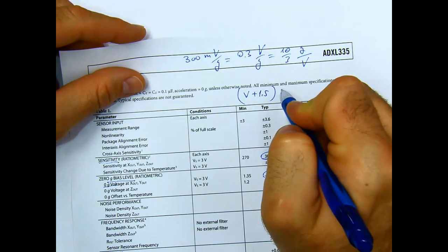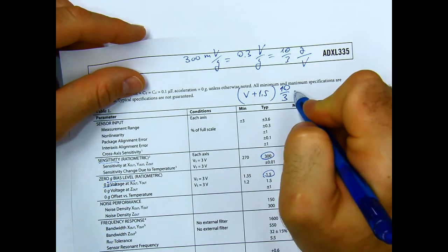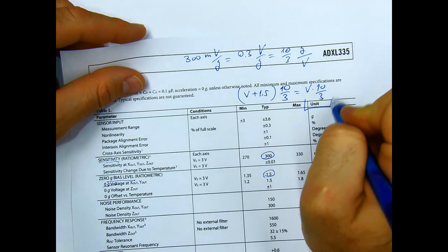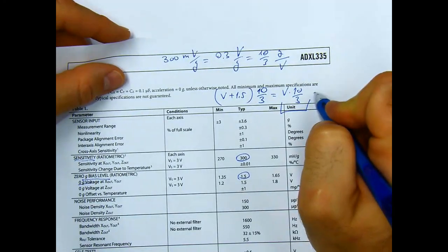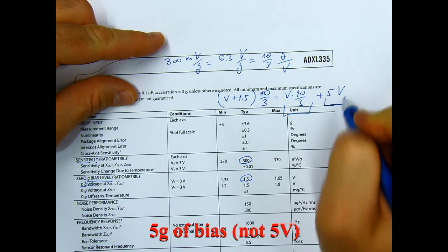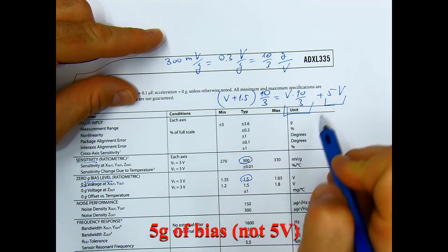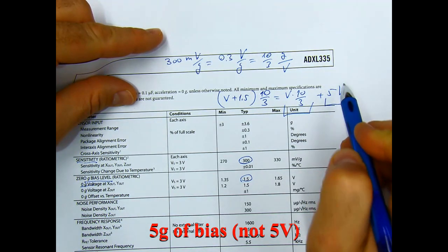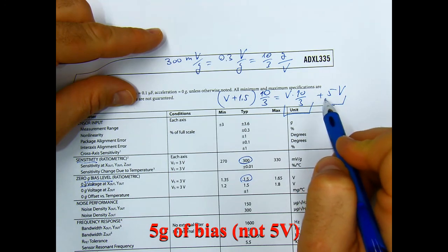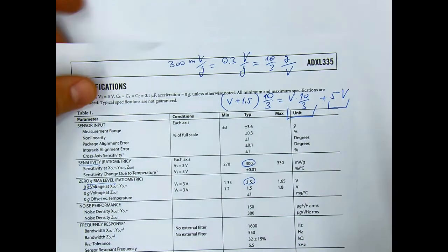All this is multiplied by the scale factor. This will be in volts, this will be already in G, plus 5 volts, which will be the bias. So you are putting this as the scale factor in the software and this as the bias. And you want to put it with the negative sign for the software to nullify this value because it has no physical meaning.